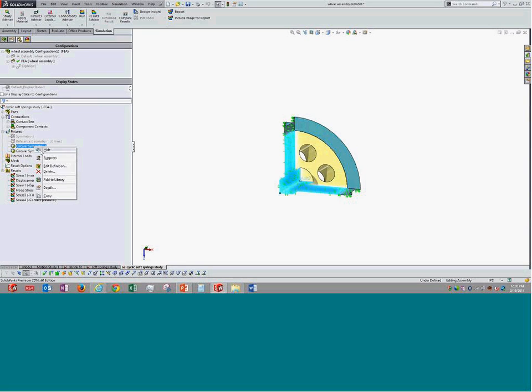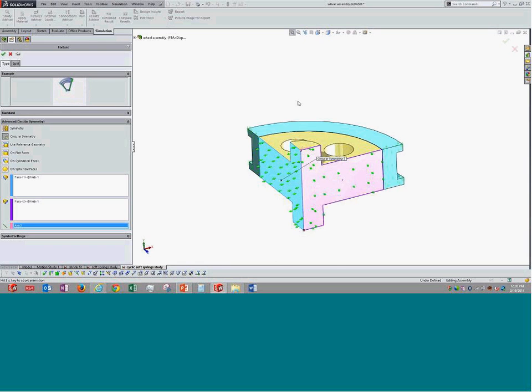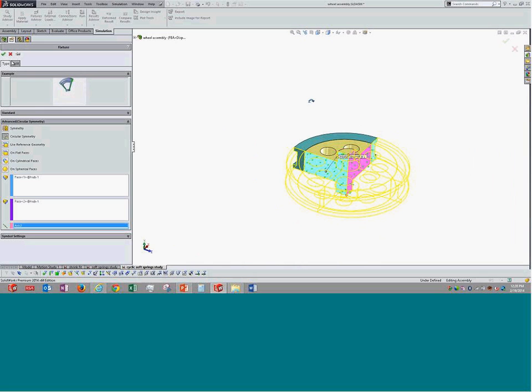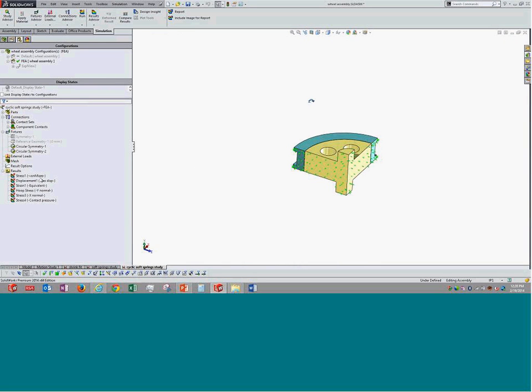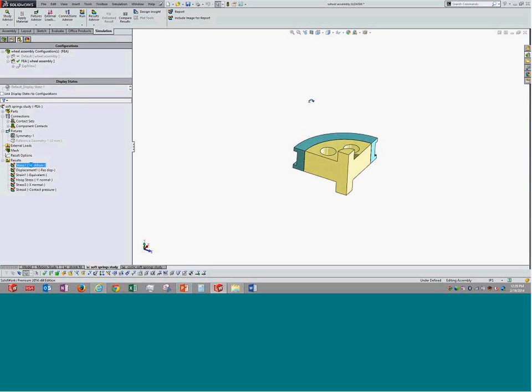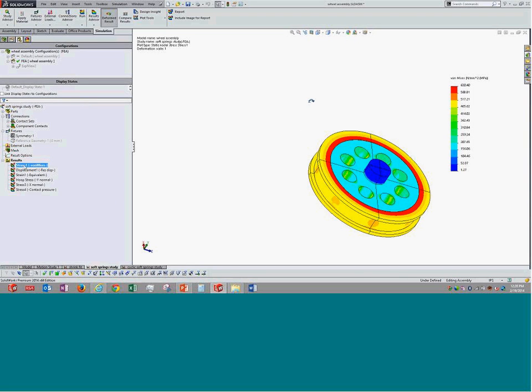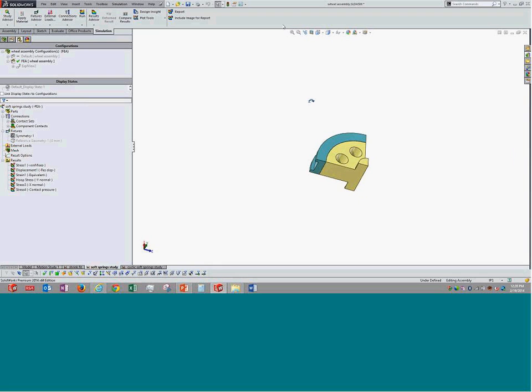However, I would suggest we can also create the full geometry and go in for circular symmetry. So each option can be used in this case, wherein we select the surfaces. If I compare the stresses with the other one, they should be almost the same. Yes, 3 megapascal. I would like to highlight there could be cases wherein symmetry cannot be used, only axisymmetry can be used.